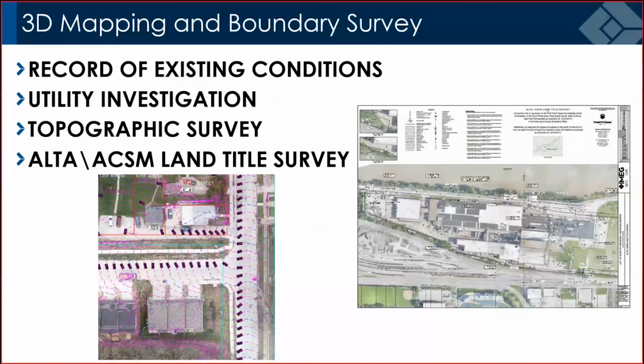3D mapping and boundary survey, right? At the time of survey, we can understand the site a little bit better. Are there utilities on the ground? Is there paint out there? We can go out there, we can fly, we can understand where some of the manholes are, where some of these utilities and structures are. This again is just supplemental to investigation out in the field.